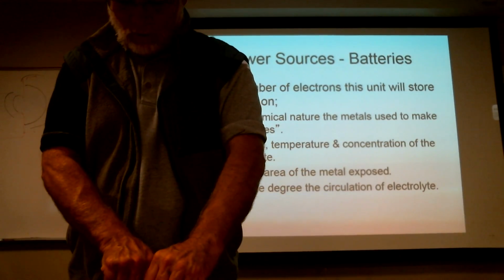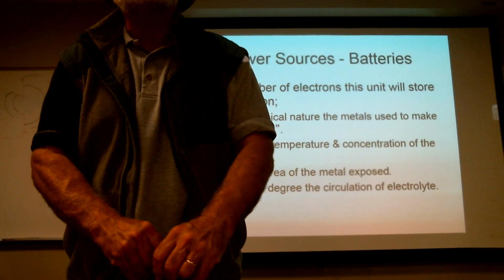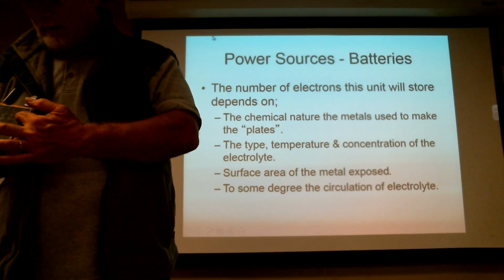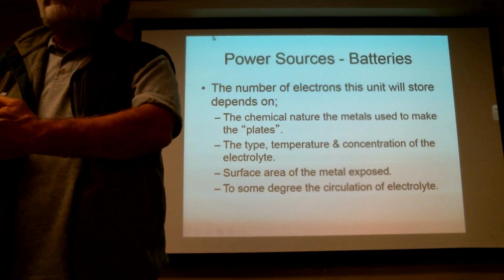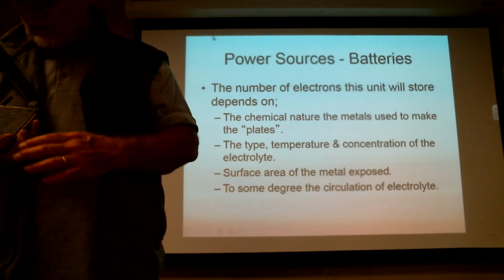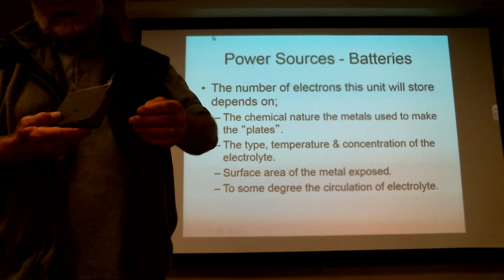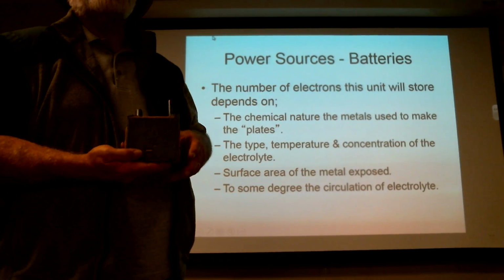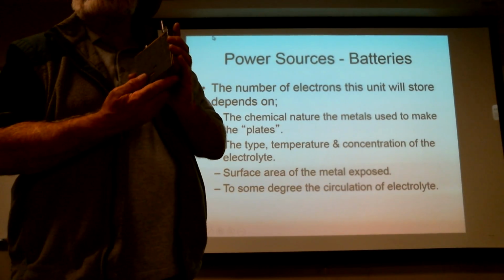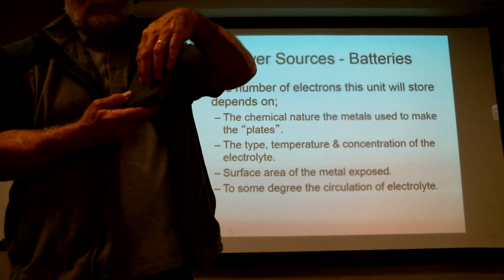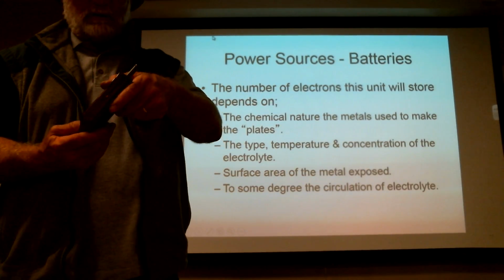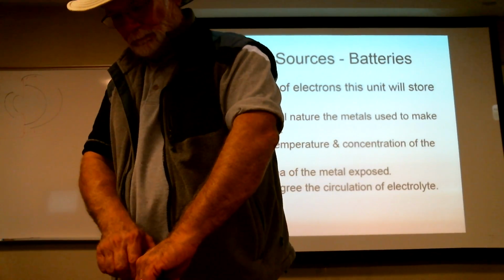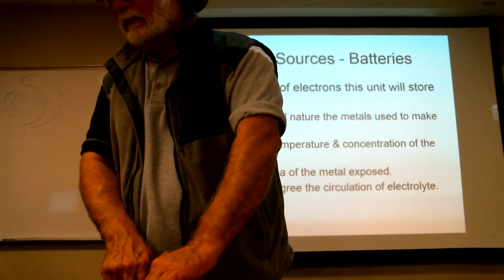Now, of course, that sponge, as it forms and unforms and forms and unforms, is going to tend to fall apart. So what I might do is take that sponge and press it into a little grid that helps hold it together. But even there, you can see some degradation occurs, right? And little bits of it fall out. That's essentially what fails the battery. Eventually, enough of these will fall out, go down to the bottom of the battery, and may even short the bottom of the cell. Okay, so we make it porous.